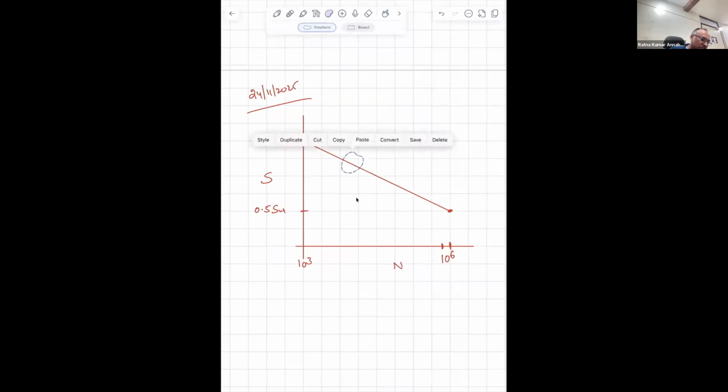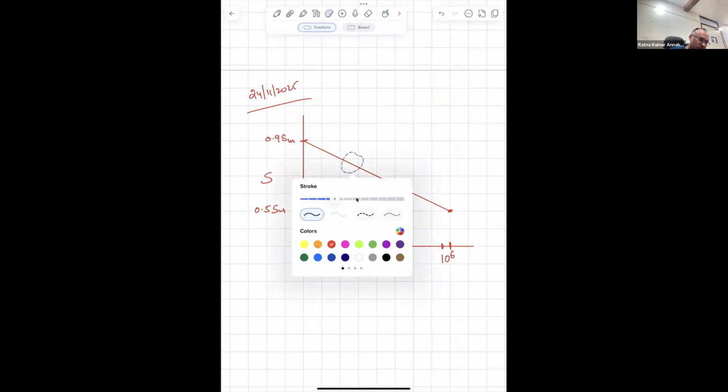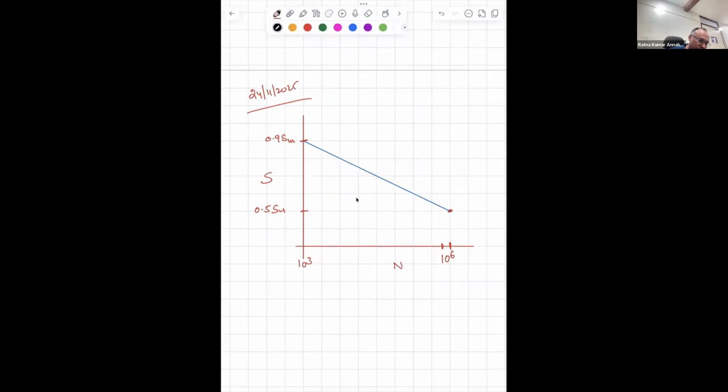So this is the scenario when sigma m is 0. This S is also nothing but stress amplitude. Either S or sigma A, both of them can be used interchangeably. These values, 0.9 SUT and 0.5 SUT, correspond to sigma m equal to 0. Is that clear?